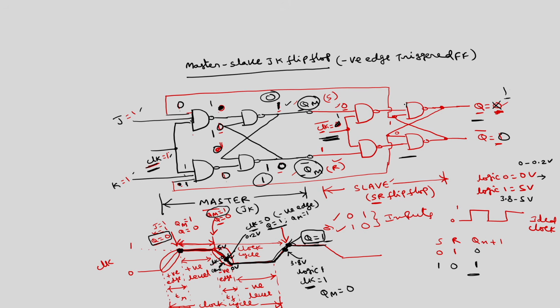Now, in addition to this, we require two more signals called preset and clear signals. Here we are going to apply the preset signal, and here the clear bar signal. This is preset bar. So regardless of J and K, if preset bar is equal to 0 and clear bar is equal to 1, what happens at this NAND gate? If one input is 0, output is 1. This 1 is tied here. This clear is 1, 1 1 becomes 0. So Q becomes 1. Okay.